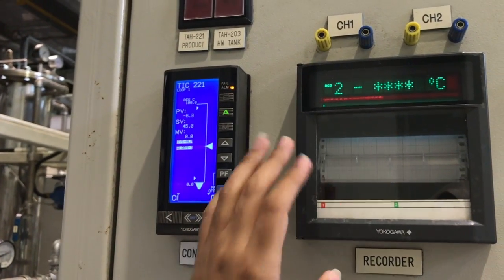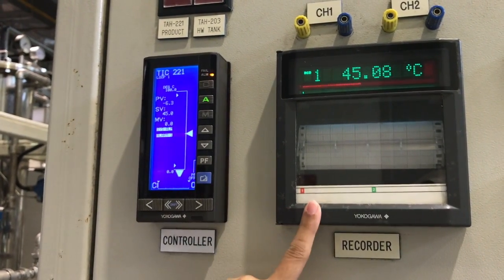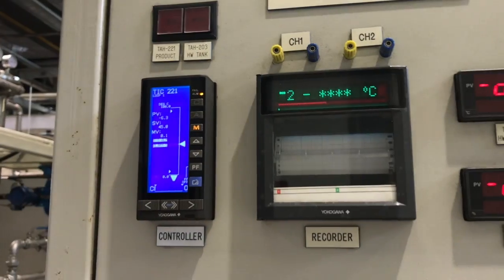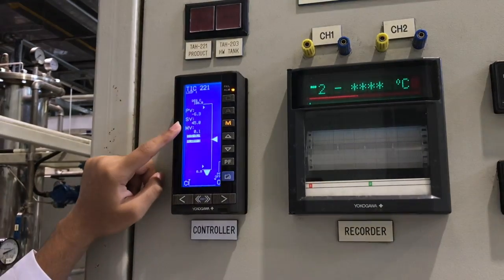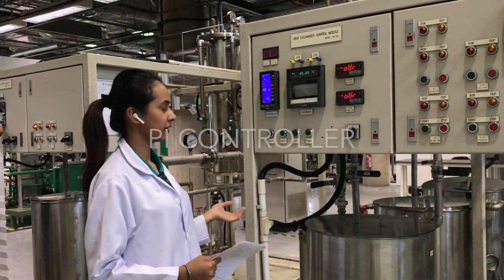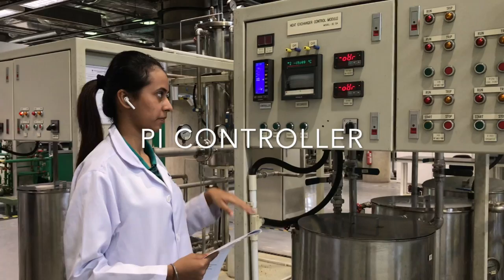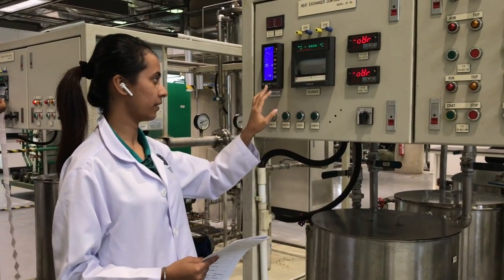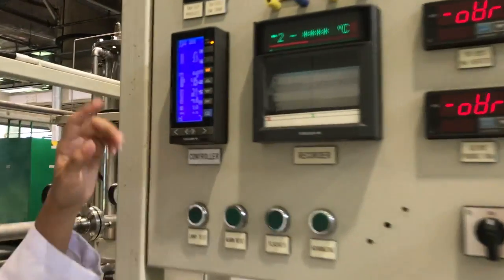Once the measurement stabilizes, we can turn off the recorder and change the control loop back into manual. After that, the experiment can be repeated using different values of P, I and D. The next part of the experiment is proportional and integral heat exchanger control. For this experiment, we are using the same procedures as the previous one, except that we are changing the values for the P, I and D values.